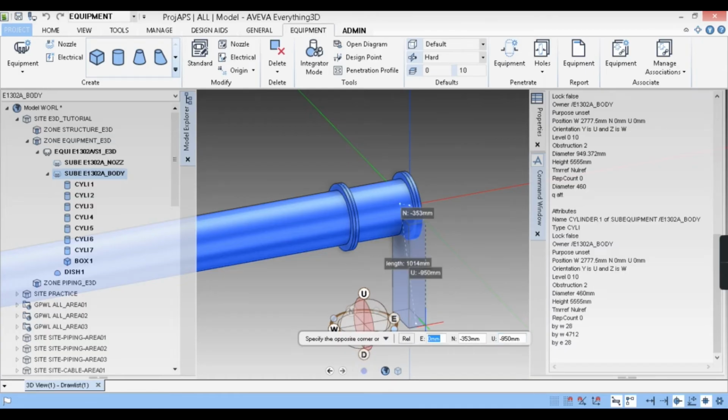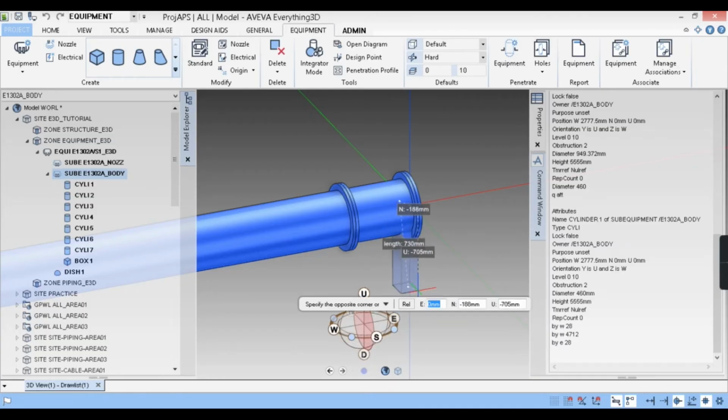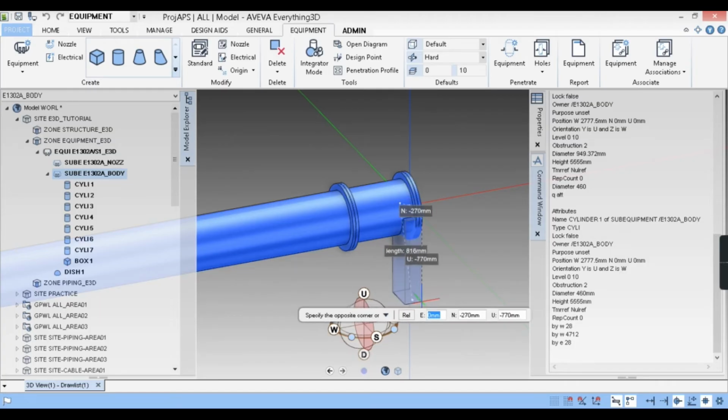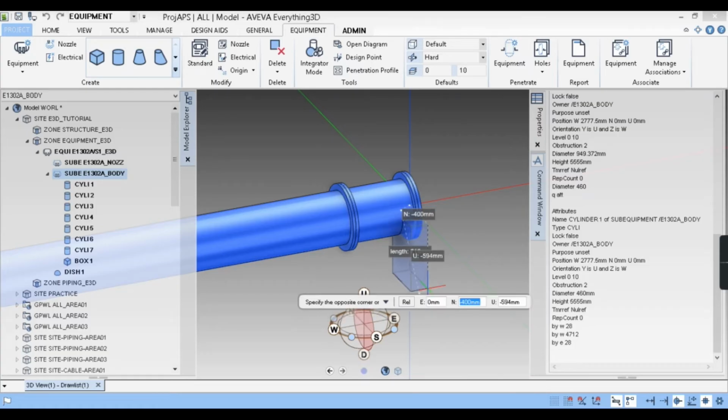This is the first corner, and the second corner will be like east, keep it as 0, because east defines the thickness and we don't have to define it now. We'll get another prompt to define that. So tab, what is north?